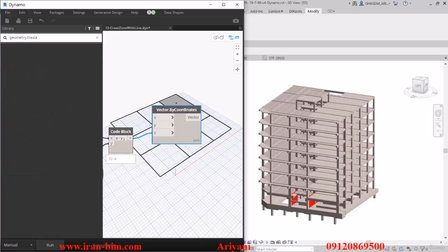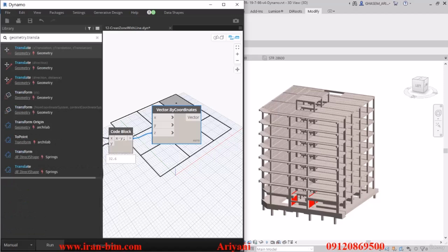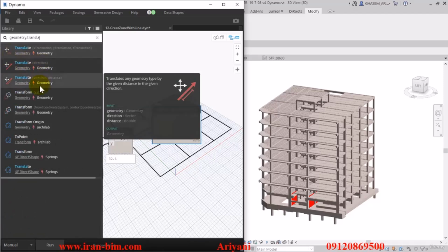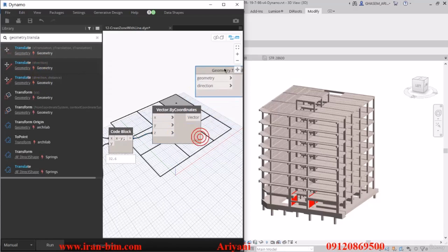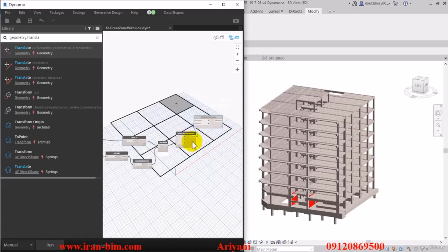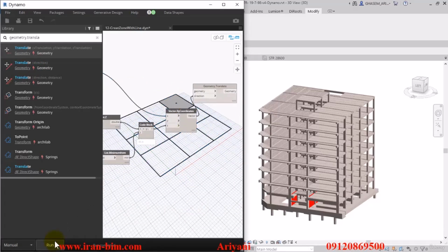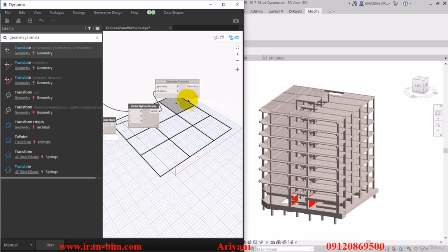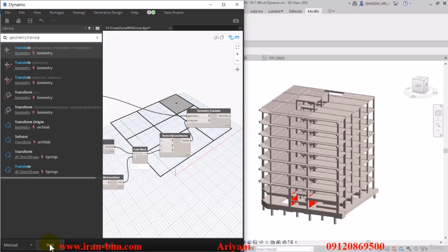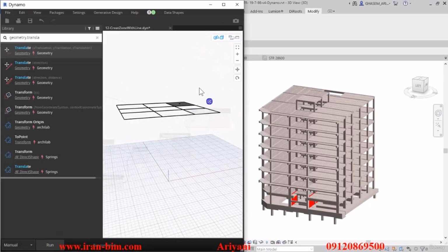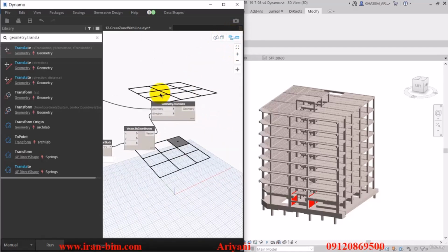Geometry.translate. Alright, now from the results that we get, we have to select the one that says translate geometry direction. Open it up, and we can connect the direction to the vector. Then for the polycurve itself, we'll go with X and run. Oh, hasn't connected yet. Oh, there was a misinput here. Connect these ones instead, and now we can press run. Alright, and now you can see we have the highest and lowest levels that we want.